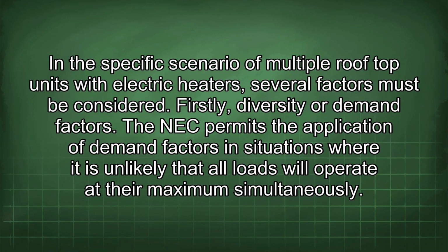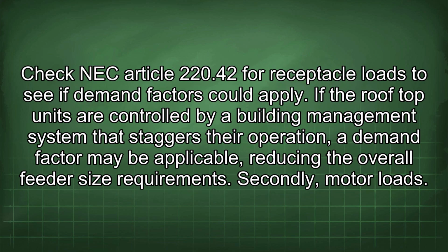In the specific scenario of multiple rooftop units with electric heaters, several factors must be considered. Firstly, diversity or demand factors. The NEC permits the application of demand factors in situations where it is unlikely that all loads will operate at their maximum simultaneously. Check NEC Article 220.42 for receptacle loads to see if demand factors could apply. If the rooftop units are controlled by a building management system that staggers their operation, a demand factor may be applicable, reducing the overall feeder size requirements.